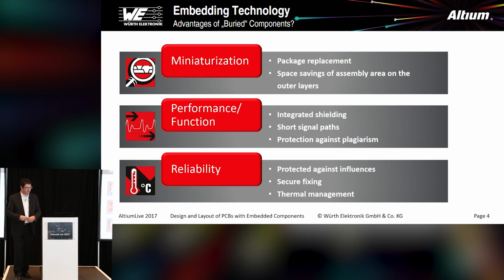And the last point basically is the thermal management. This is where all the MOSFETs, IGBTs come into play. There are some IC manufacturers already out there who can work with copper on their bare dies. So we can directly connect them with the copper from the PCB. So we have a direct copper connection and a very good way to get the heat out of the boards.